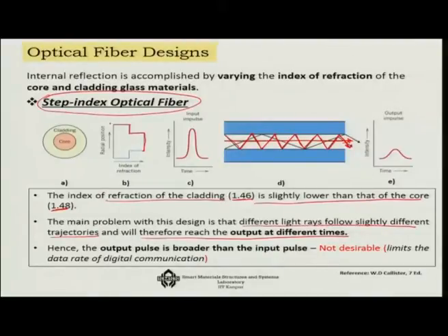So this slight delay will create, if this is my input impulse, an output that looks like this. That means the output pulse will be broader than the input pulse, which is not desirable, because this actually limits the data rate of digital communication.